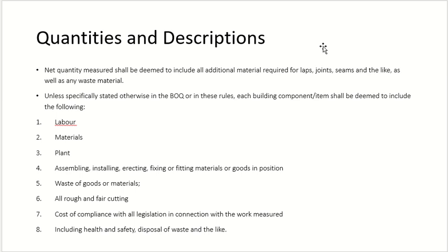So the responsibility of the contractor is to send the material for testing. Some testing is done on the site. For some testing, he has to send the sample. So this whole process is part of the pricing. And in some cases, we need to do the surveys. Is the level sufficient or not? Is the wall straight or not? Is the beam in the alignment or not? We don't need tests for that. We do the surveys.